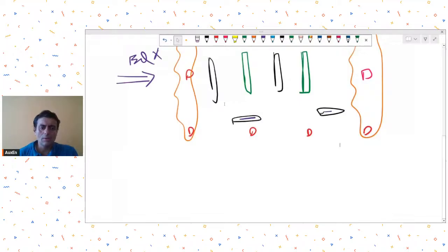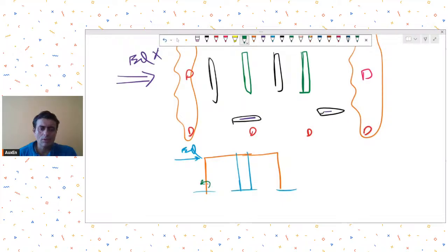So all of us know how earthquake force or how lateral forces are resisted. Lateral forces are resisted in two ways. So if there was an EQ force acting like this, one way to resist earthquake forces is through development of end moments. Now, let's say this is my shear wall that will resist M3, but this will be of a very high magnitude because the shear wall has a very large stiffness. So this M3 will be numerically significantly high as compared to M1, M2.